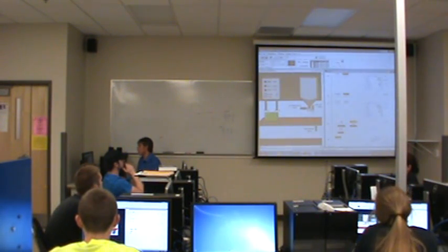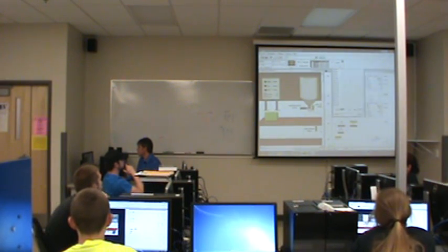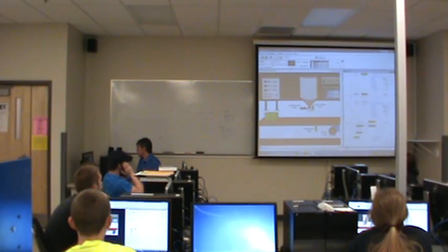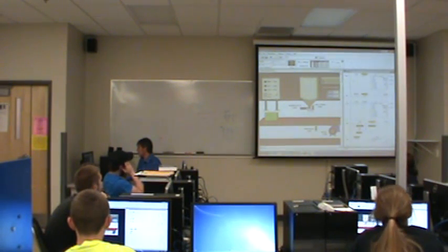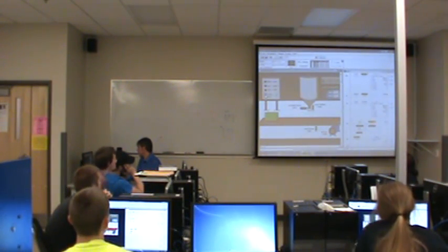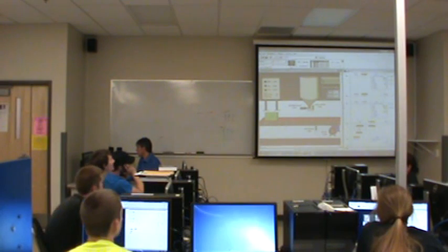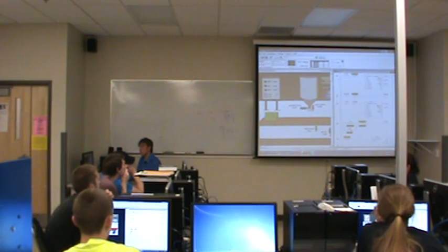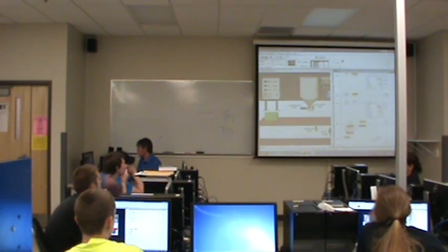Now before I hit start, I'm going to go into memory and make sure my lists are still as I expect. If I can get there. Can't see these up here, but these down here look right. I'm happy with that. Now as soon as I hit the start button, that should seal in the circuit, which should activate these sequence instructions, and it should start working. And it didn't. Wow. Actually, what happened is, notice I did not seal in with the appropriate bit. I forgot to change this address to 2/2.